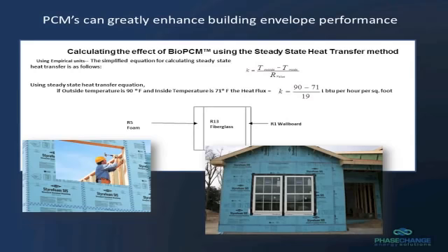The test facility is at Fletcher's Insulation in Sydney here. We ran a test on phase change material. Normally you put an insulation mat inside the machine. It stabilises the temperature at the top, I think at about 30 degrees, and it has a sensor at the bottom at 20 degrees. It stabilizes the insulation, then it does a test, and it cycles it and measures the R value. It comes out with R2 or R3.